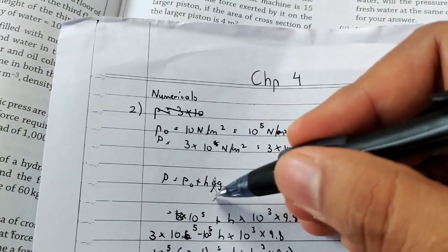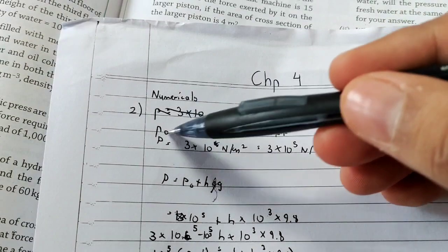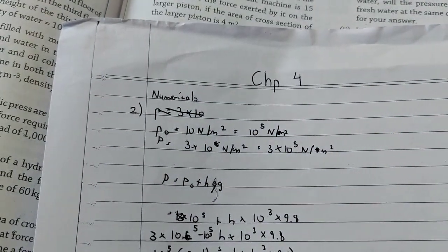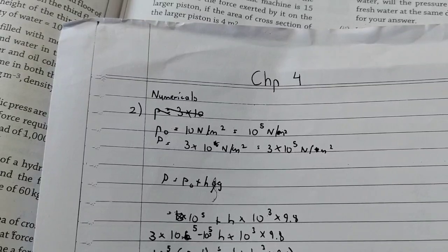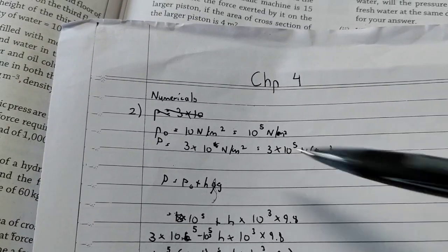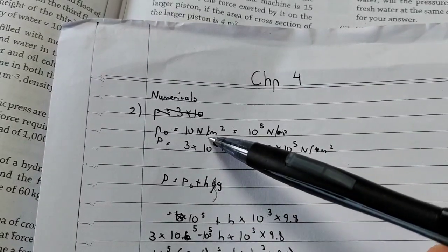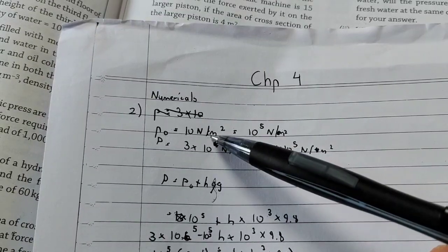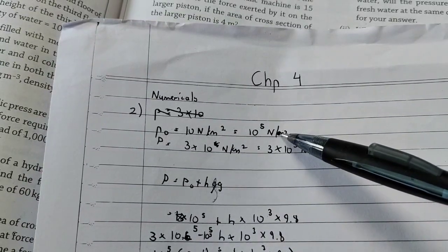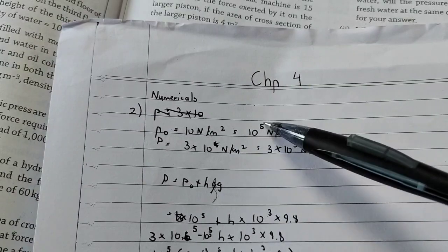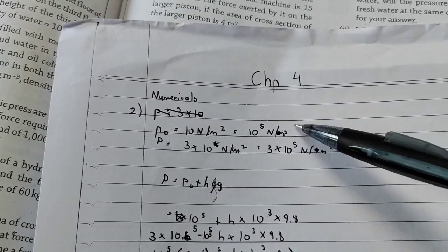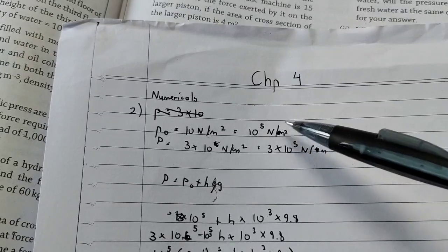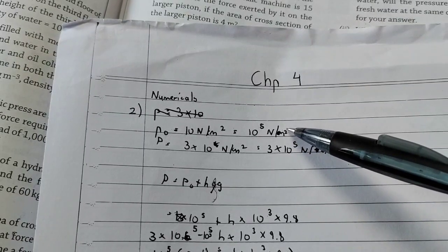This should be a rho, density. Now, density is given as 10 raised to 3 kilogram per meter cube, so that is in SI unit. But the atmospheric pressure wasn't. It was Newton per centimeter squared, so we need to convert it to meter squared. That will be multiplied by 10 raised to 4, so totally it becomes 10 raised to 5 Newton per meter square, also called 1 lakh Pascal, which is indeed 1 atm at sea level.